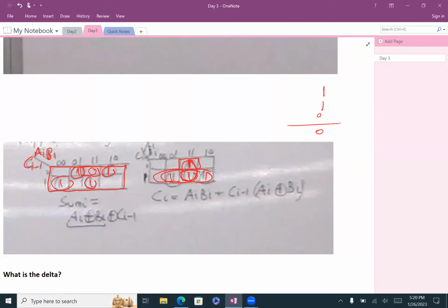So how can we do that? That's the approach. Simply we need something called a look ahead unit. Correct? Carry look ahead unit. And what will this unit provide to us? It's going to give us C0, C1, C2, and C3 at the same time.